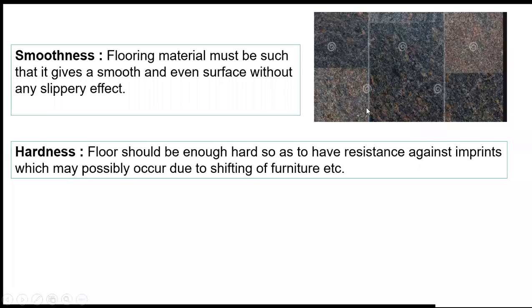Now, hardness. Yes, your floor should be hard enough to have resistance against imprints, which may occur due to the shifting of furniture. In any residential building or any other type of building, the floor should have sufficient hardness. Otherwise, in a residential building, many times you have to shift your equipment, your furniture, your beds from one room to another room. Normally we slide the almirah, etc.